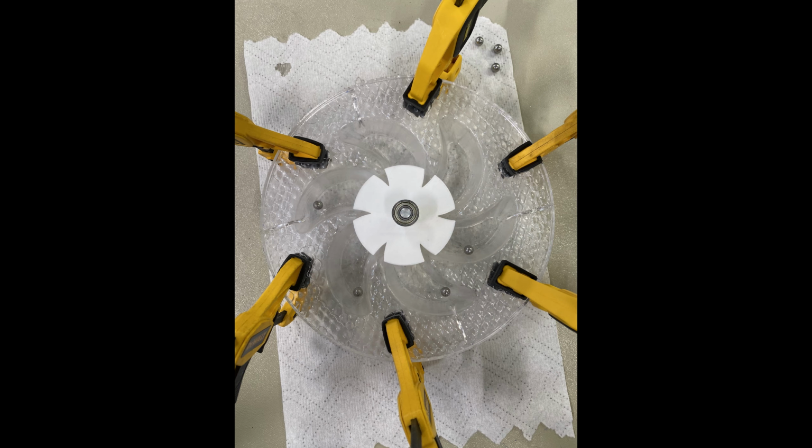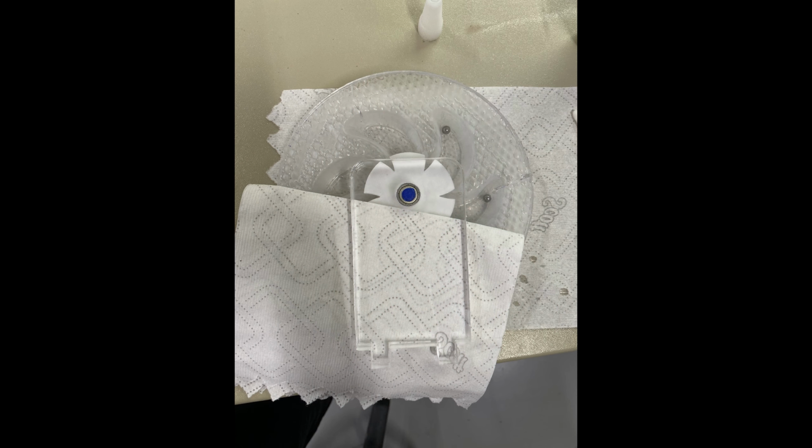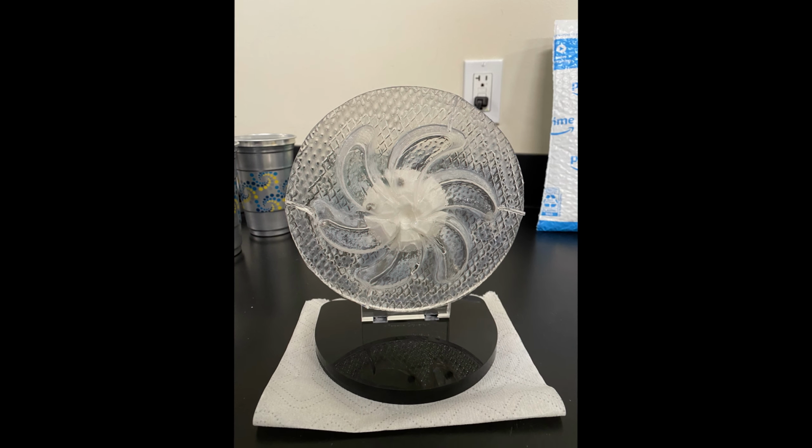As I waited for this glue to dry, I also glued the non-bearing side of the crankshaft into a hole in the center of the laser-cut acrylic disc. After this step, I attached the acrylic support piece to the bearing. I placed a folded paper towel in between the two pieces while the glue dried to keep optimal spacing and prevent rubbing. Lastly, I slotted the support piece into the base and added glue for more stability.